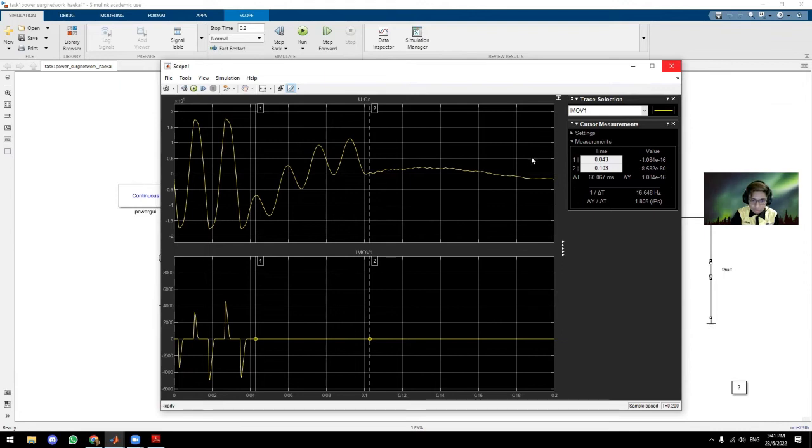This is due to the protection of the MOV, and during that time the current value is equal to 0 from the starting time of 0.04. So during the clearance, the voltage is at the highest peak of the voltage reading, which we get at 3.121 kilovolt.